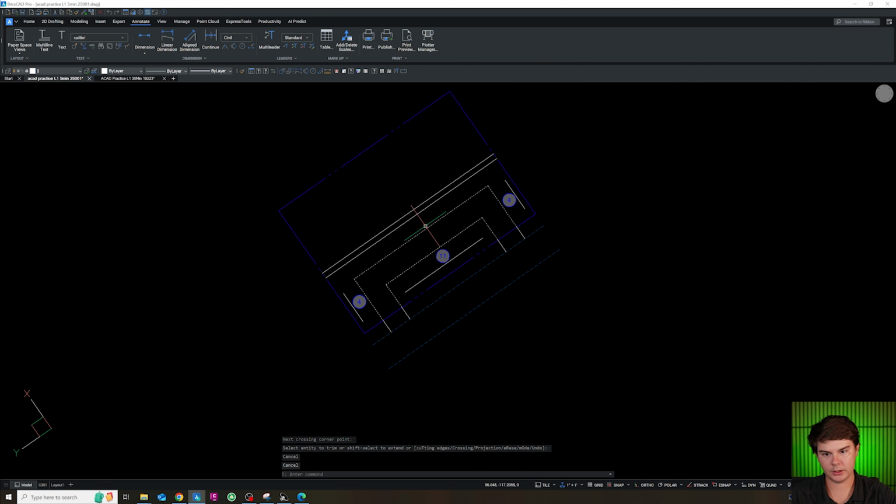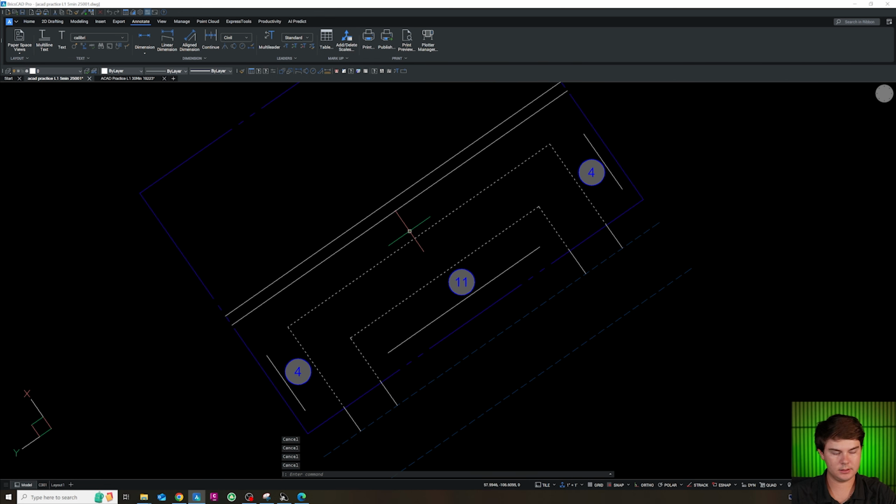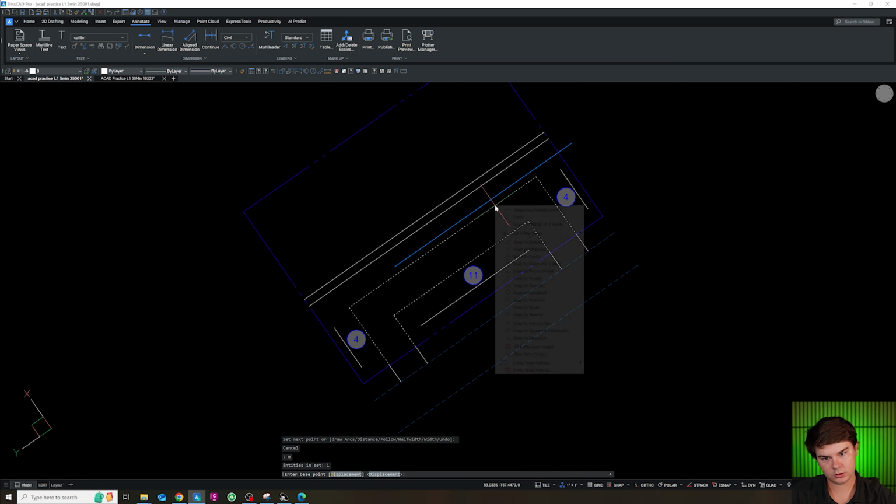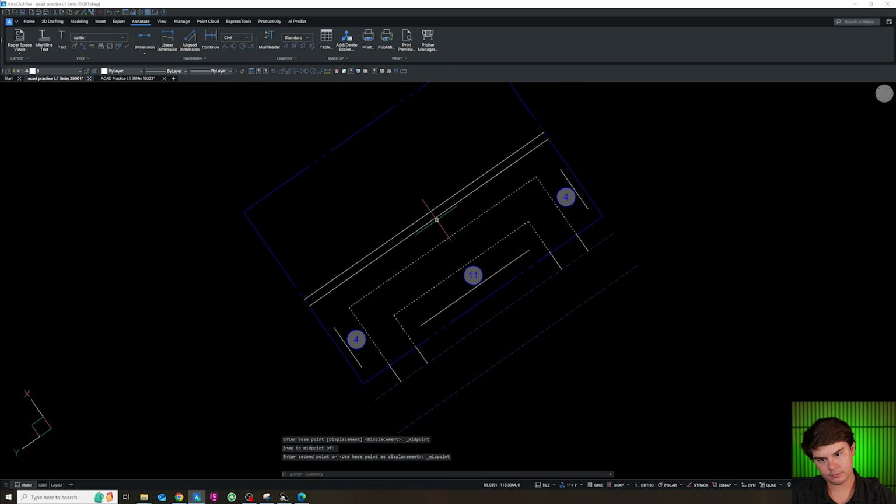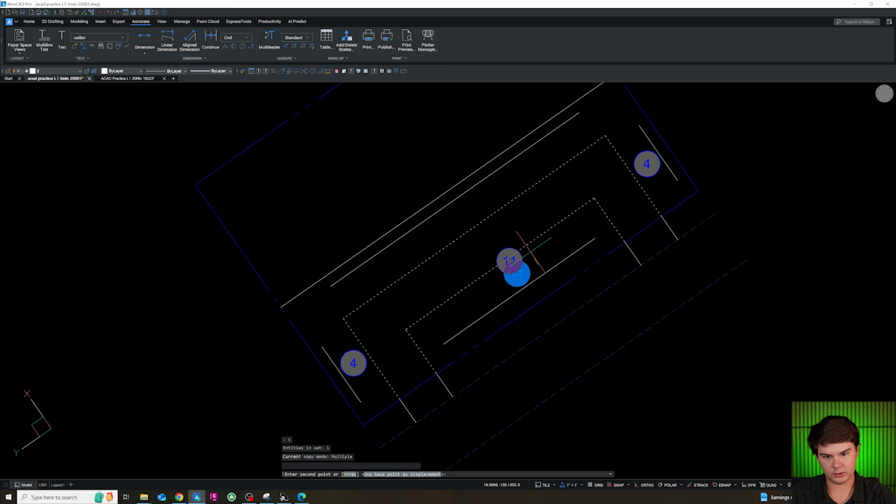We've got parking. Now we want to show 18 spots here. So 18 times 9, 162. So we'll hold Shift to draw ortho, 162 feet. And I'm going to draw this to the midpoint here. Delete this. Now we have our 18 spaces here.